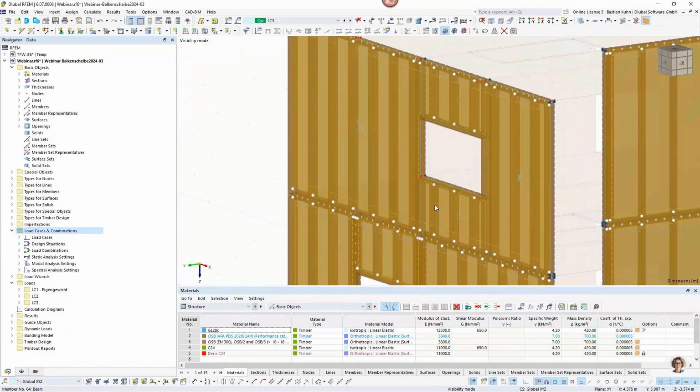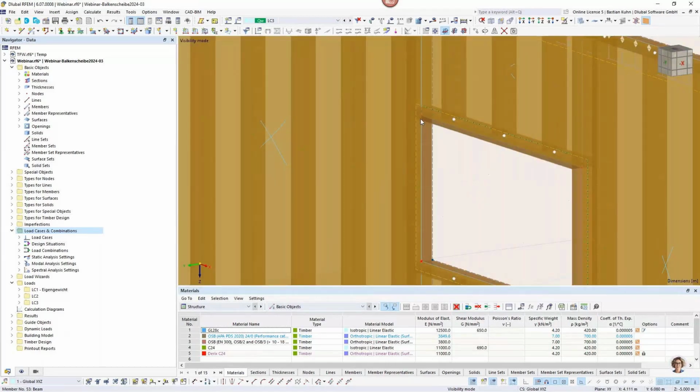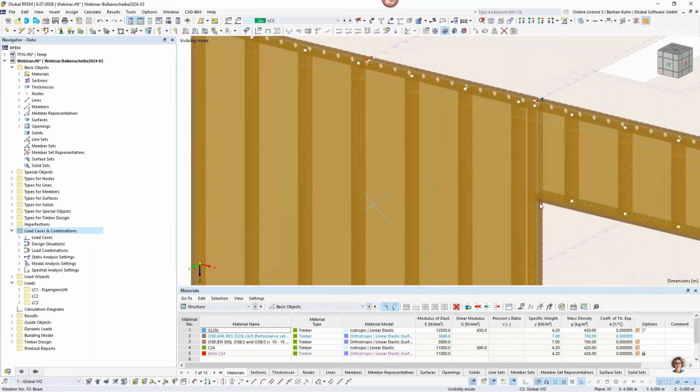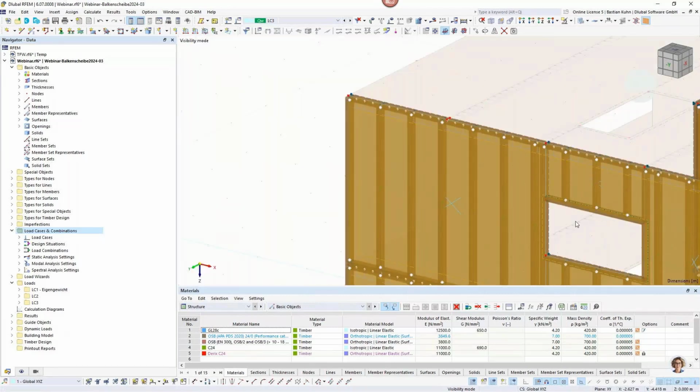Then what we do here in Europe is that we are using the top beam, or how you call it, on this window, and move it to the next stud. That's one of the possible constructions, and then it's a complete shear stiff, and of course it's nailed on every part wherever our OSB plates are connected or coming together, and there's always a beam or a post behind it. That's where it can be nailed on.